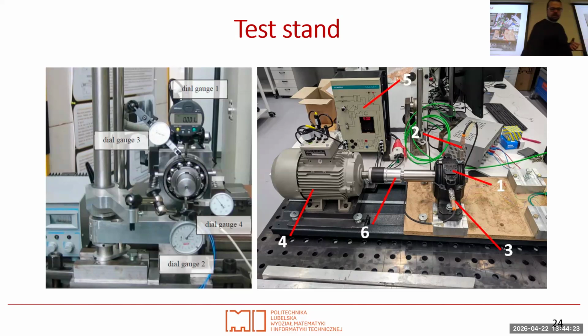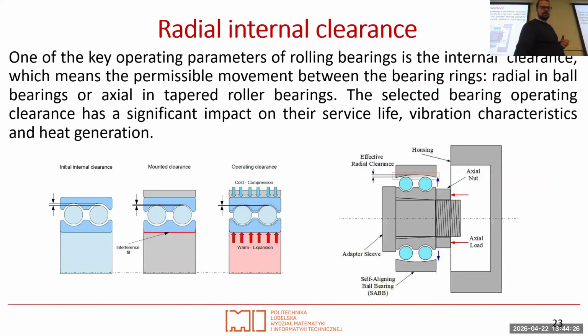And in one bearing, what I showed you then, because the cone over here is a tapered cone, so it's not a flat one. It's tapered. So it was possible to put, for example, the initial one, just to put the axial and block it, but we kept the clearance as a mounted one. During the test, we also learned the thermal expansion, because the linear expansion of the metals was possible to measure as well.